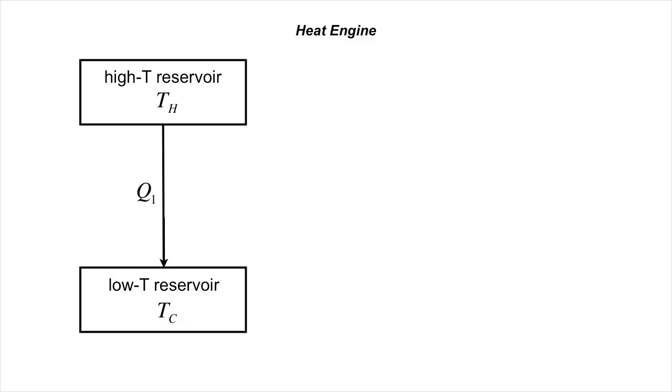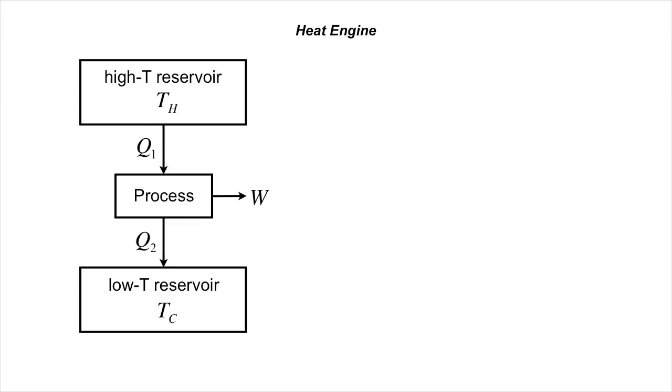Okay, with that issue out of the way, let's focus in this episode on one particular type of energy conversion process, called a heat engine, which converts a thermal energy source into work, or vice versa. To begin, imagine we have two reservoirs, maintained at uniform and constant temperatures, TH and TC, where TH is greater than TC. If provided a mechanism, heat will tend to flow irreversibly from hot to cold, creating entropy. The purpose of a heat engine is to harness this tendency of nature and extract some work.